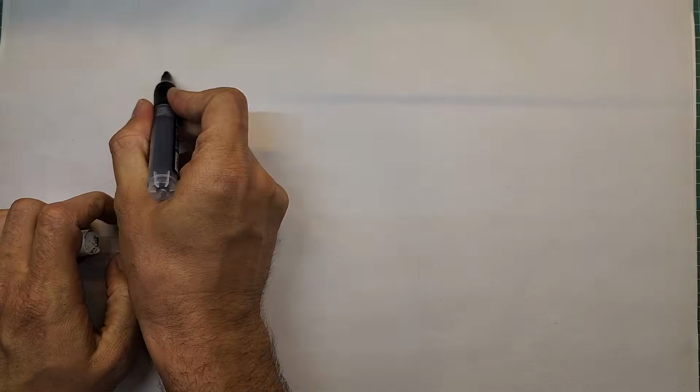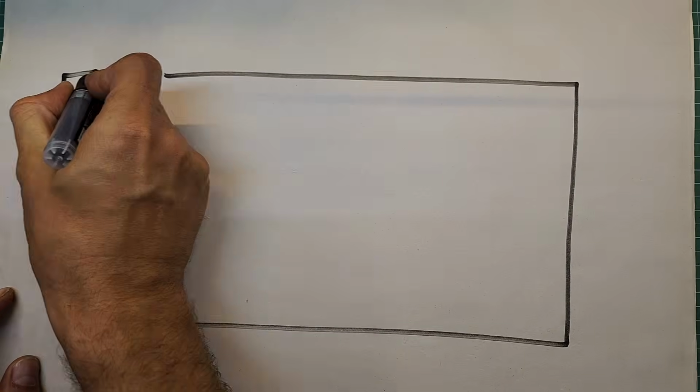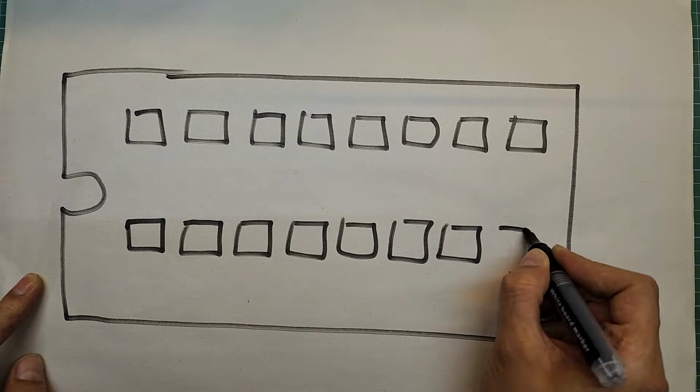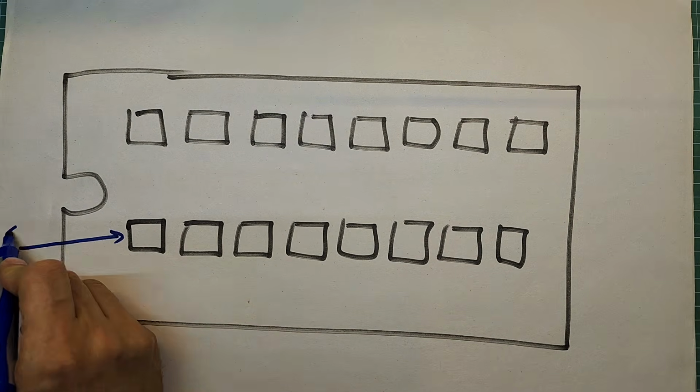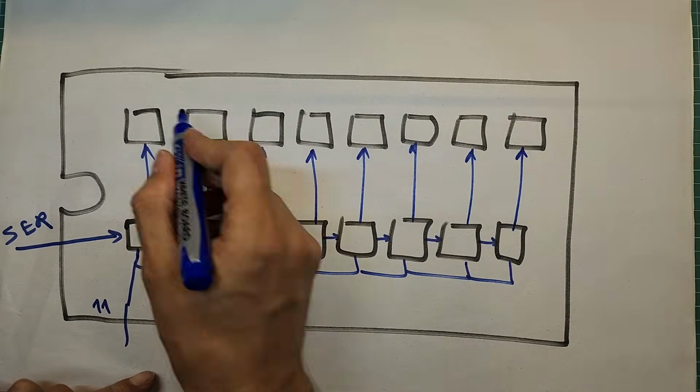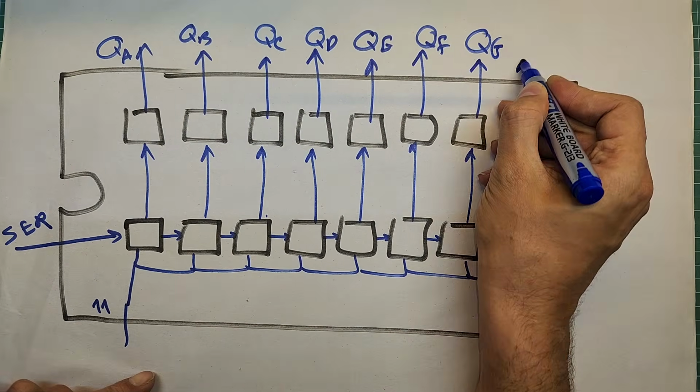In the first version of the 10-channel lighting system project, I didn't do this and it caused an undefined pattern to be shown at device startup. I really didn't like that situation at all. On top of that, since I used the same IC to determine the status of the channels, at device startup some channels would randomly turn on and some other channels would randomly turn off until the microcontroller put the appropriate value on the IC. This was even worse than showing an inappropriate pattern on the 7-segment display.